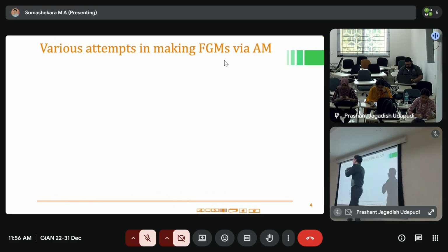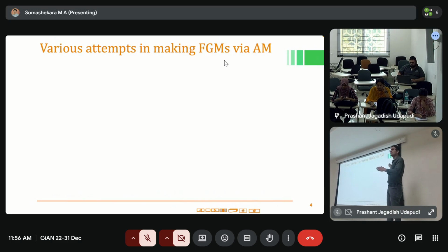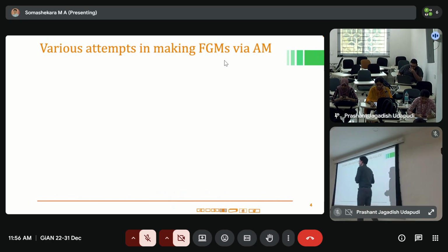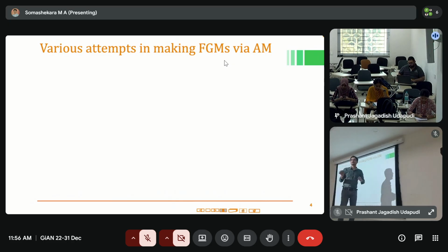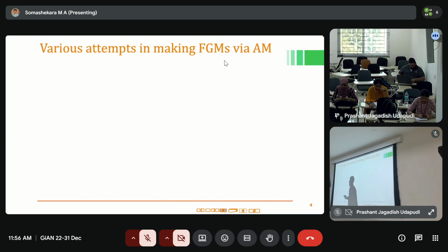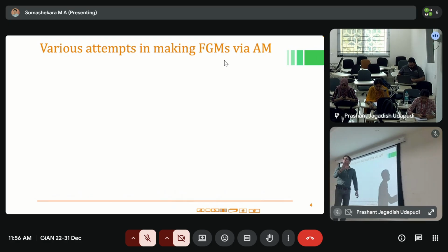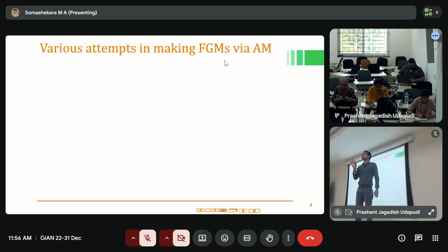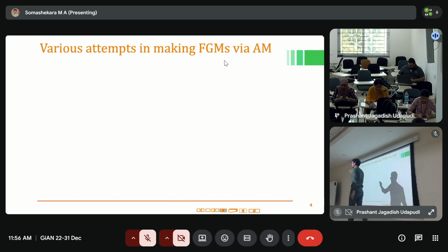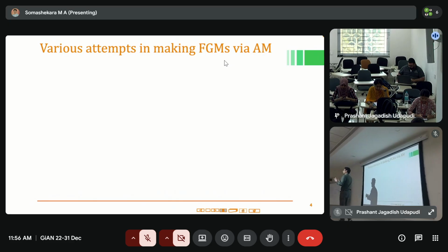As I said, why we use additive manufacturing for this kind of structure, one simple reason is you can control your materials. Why? Because we are only adding material as much as is required. We are only fusing as much as is required, wherein you can easily control what material is supposed to go at a particular location, or at a particular moment, or in a component.